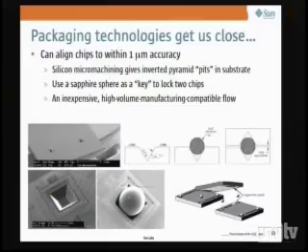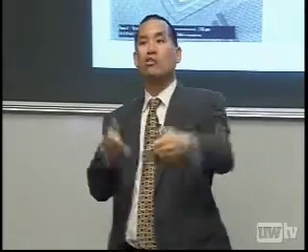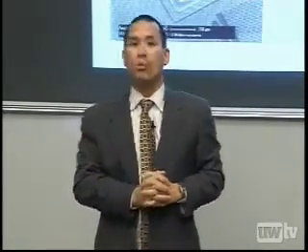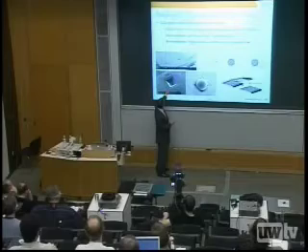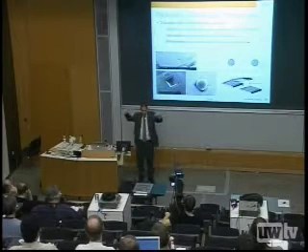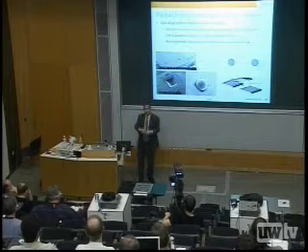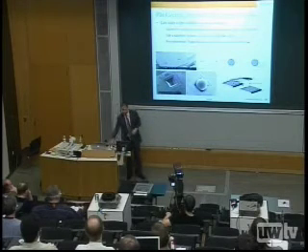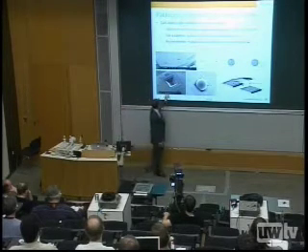So imagine you take a silicon chip and you expose a square of the raw silicon, and you dunk it in some solution that's an etchant, and the etchant will attack down to the 111 crystal plane. Okay? Well, when you dunk it in the solution, it's going to etch a perfectly inverted pyramidal structure. It's a self-terminating etch because you'll eventually just end at that thing because it's a selective etch of very high selectivity, and that makes for me a pyramid.